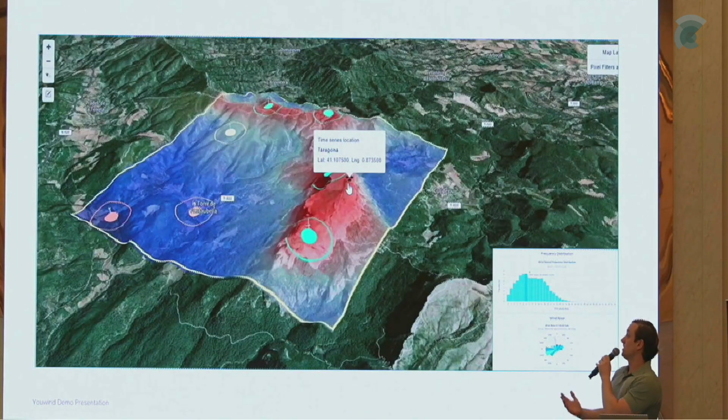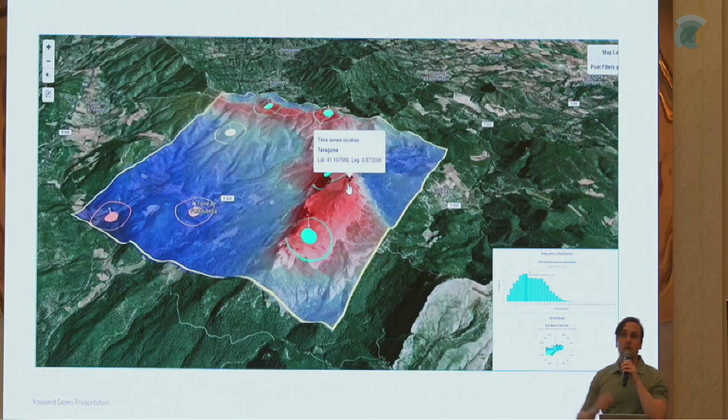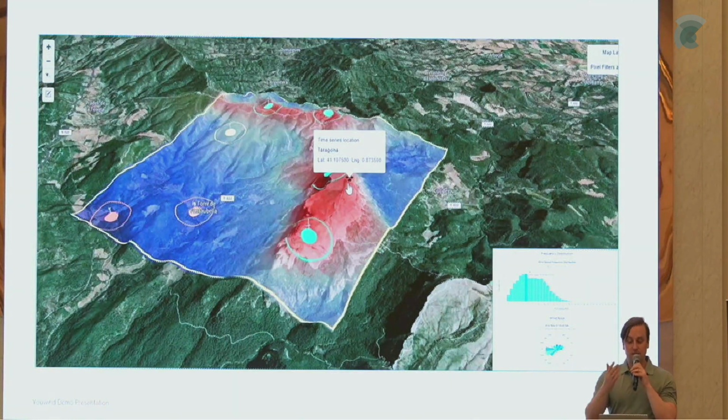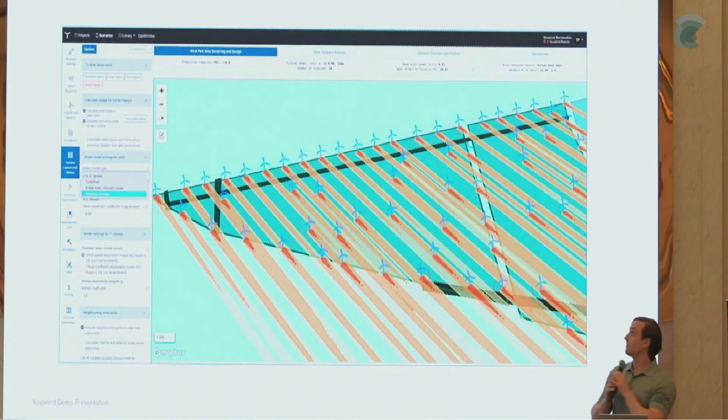For onshore, this is also the same. So this is a typical site that we have, for example, an area in Spain. Here you lay over in 3D your grid map, your farm map, your WRG file, and you basically say, find me the best area within this zone, see how many turbines can fit, and then optimize that in terms of finalizing the layout design to minimize wake losses.